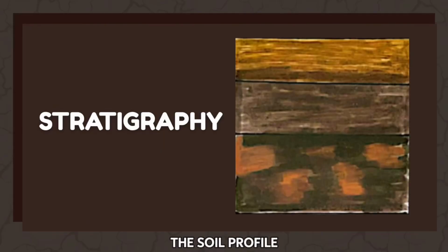The soil profile in borehole number 1 showed a gradual transition from loose, coarse-grained topsoil to denser and more cohesive clay-like material with increasing depth. The upper layer consisted of light brown soil mixed with roots, leaves, and small rocks, while the deeper layers became darker, denser, and more difficult to excavate.